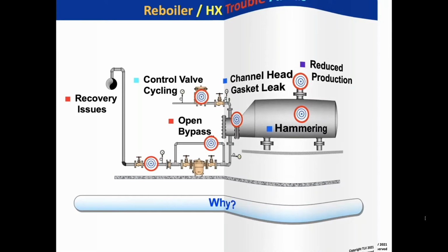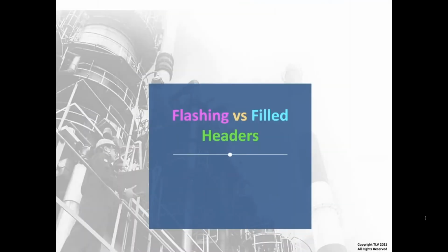Well, to understand, we're going to take a look at several concepts. The first one is flashing versus filled condensate headers. And I want to talk about a phenomenon known as collapse hammer.